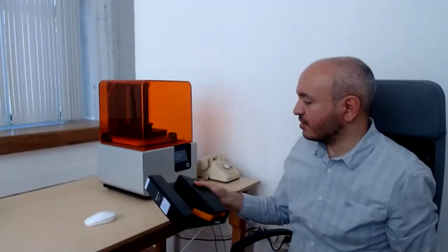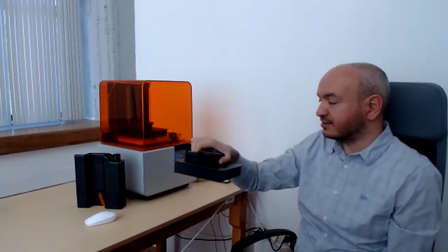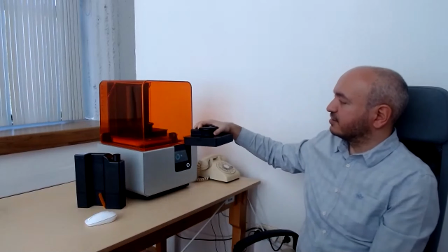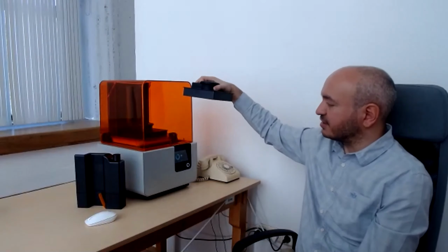Obviously, before using, you need to do some shaking so that you have homogeneous material inside. Otherwise, some parts might have little polymers and some parts might have some water. So before using it, it's better to do some shaking and try to homogenize the photopolymers inside. The rest is not that complicated. We don't have any X or Y axis in this one, just the table, or wheel plate. This one is called a wheel plate, and it moves upwards and downwards.